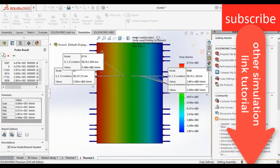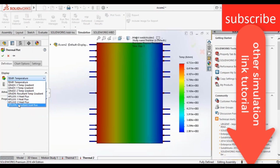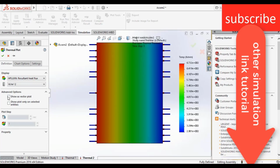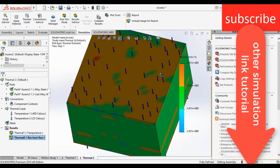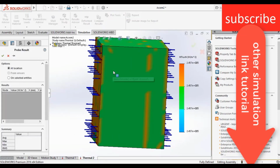Now let's see how to see heat flux. Click on temperature, click on heat flux resultant, click show as vector plot. Let's see without vector plot. Click OK. Here you will see the heat flux plot. Click on probe, click on it.